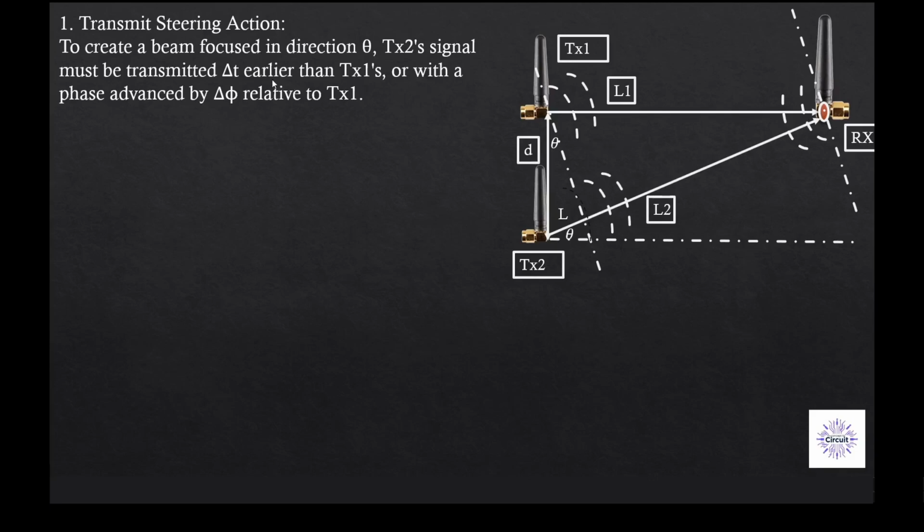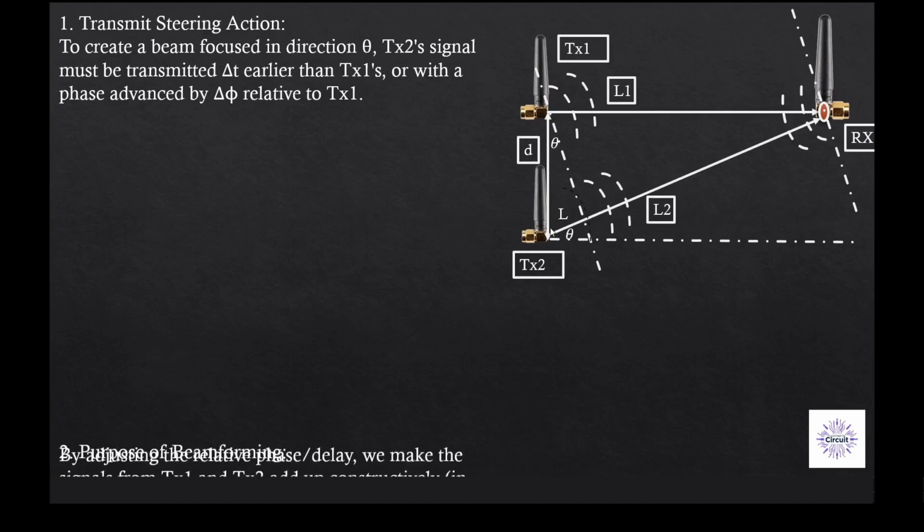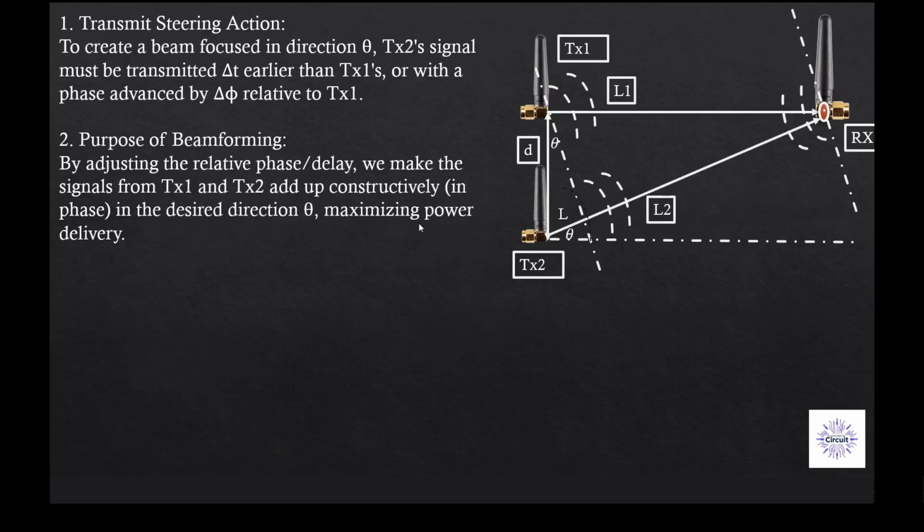This can be adjusted by changing the time relationship of the transmitted signals, which at a given frequency is also transferable to a phase relationship between these two. So basically, when we want to initialize a transmission, we can sweep the phase, time, or delay relationship of the channels to maximize the delivered power at the receiver.